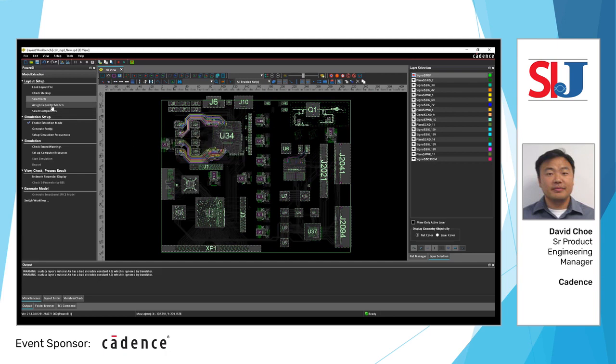So the next thing we can do is assign capacitor models if we'd like. We can assign any sort of spice model or touchstone file, anything of that sort can be assigned very easily. The spice models are not limited to just some definitions of R, L, and C. You can put any sort of passive network in any combination. The nodes can be expressed in any sort of spice that you can think of. This extraction mode is already enabled, so the next thing you need to do is generate ports.